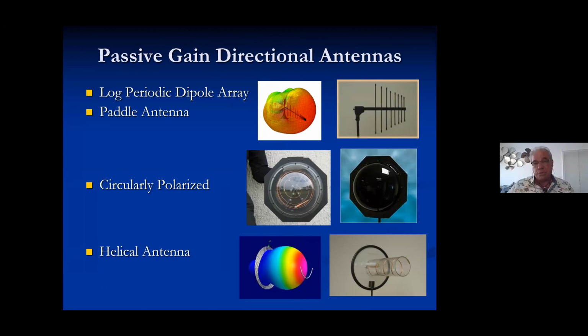So that top one there, these are all directional antennas. By the way, it is passive gain, which means that you'll get anywhere from 6 dB to as high as 12 dB of gain over a dipole. So that's a lot of forward gain with no RF noise from an amplifier. I always carry a couple of those Shure inline amps that are powered up the coax by 12 volts DC, and they have a 3 dB and a 6 dB switch. PWS makes them as well with a 5 dB and a 15 dB. There's a couple of manufacturers that make their own version of that. I love carrying those, but they add RF noise.